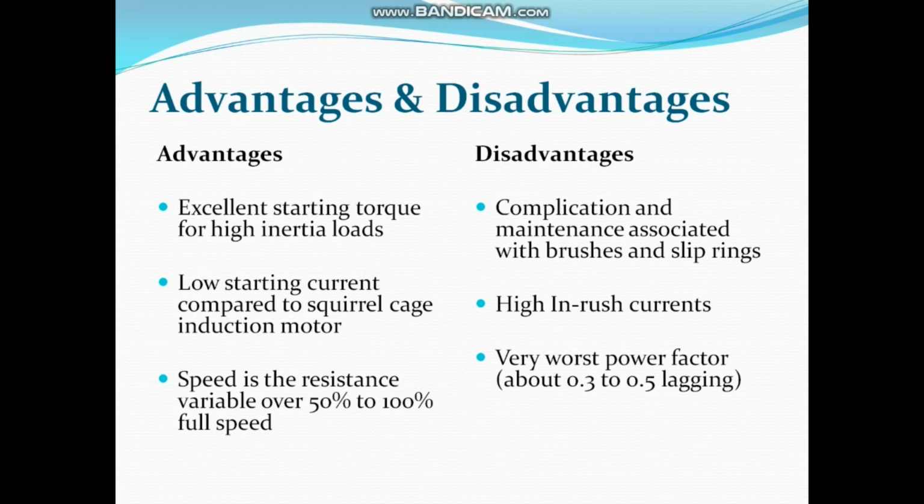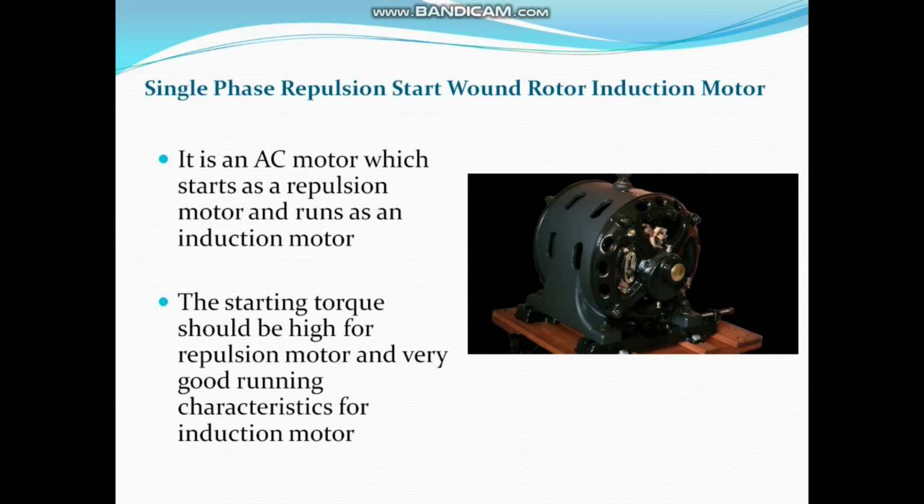Complication and maintenance associated with brushes and slip rings, high inrush currents, and very poor power factor of about 0.3 to 0.5 lagging are the various disadvantages.